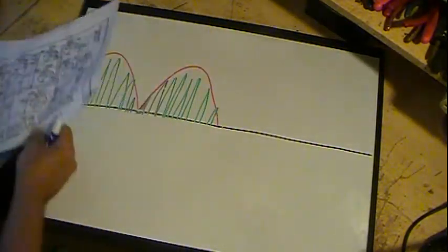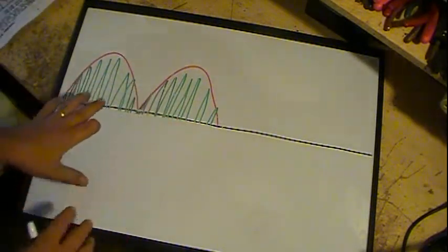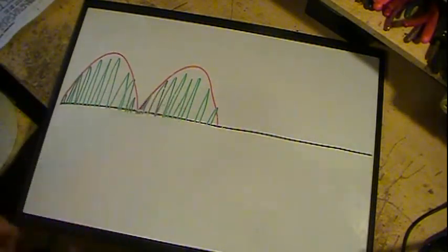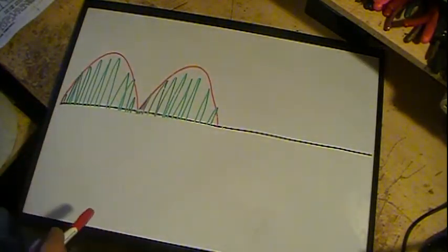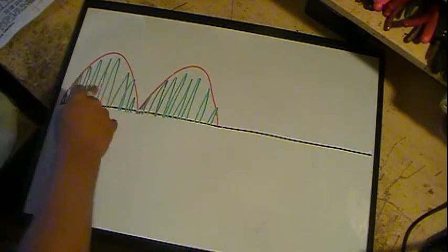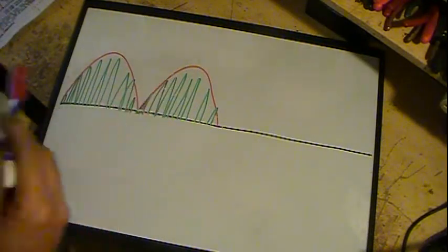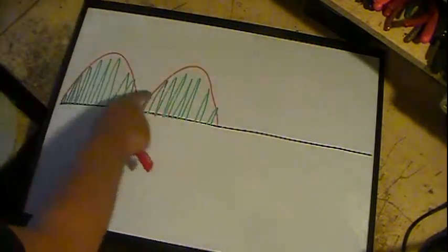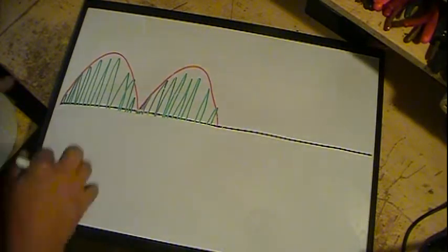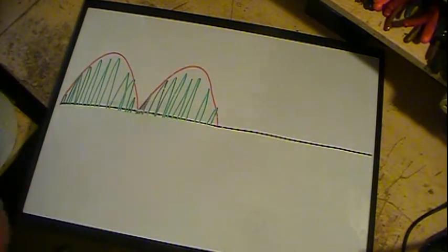Now, this is all fine and dandy. I can amplify this now, but I've got this noise in here. I've got to get rid of the noise. This 455 is going to cause all kinds of headaches and harmonics and problems and heat in these output tubes, and it creates noise and distortion, and I've got to get rid of it. I don't want that in there. So how do I get rid of it? Well, the simplest way of doing that is to filter it.